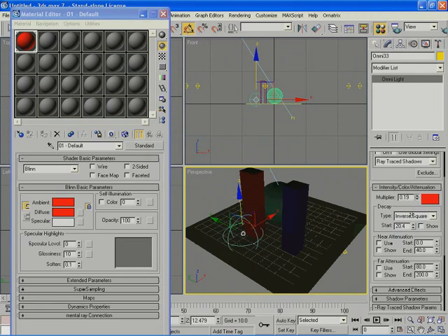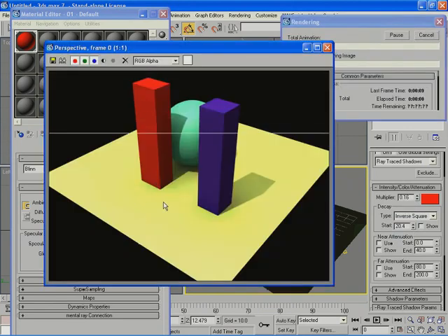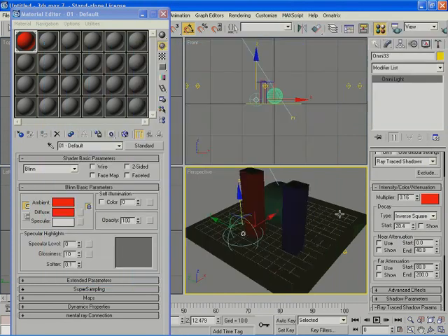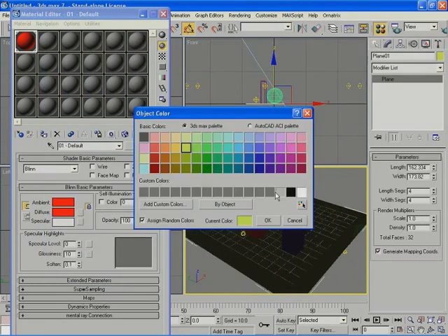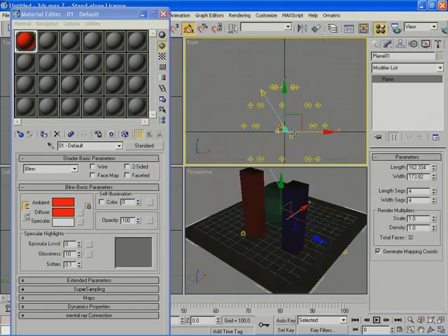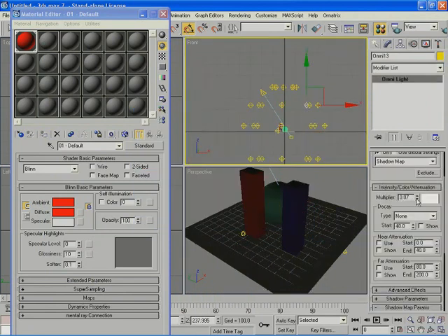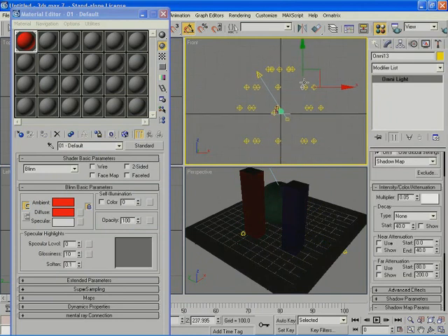Okay, I start to get some brightness down here. Let's make the color of this surface gray so that it's neutral. We don't see its actual color. I'm going to lower down the multiplier of the omni-lights. Take this and move it up and increase the start range and render.